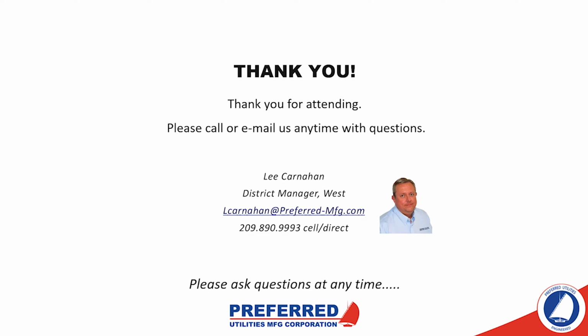On the existing UST systems, most of them installed in California right now, the vacuum for the vacuum monitoring system is actually generated by the submersible turbine pump. In our case, we have a vacuum pump on board the system, so we don't have to run the pumps in order to generate that vacuum. So that's probably the most fundamental difference between our system and the others currently available.